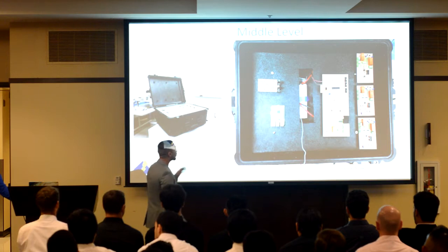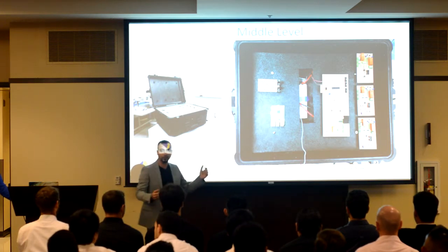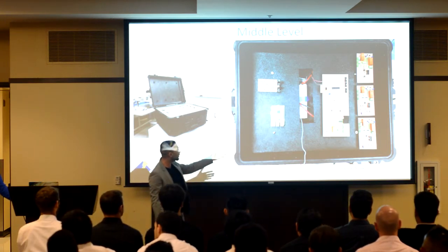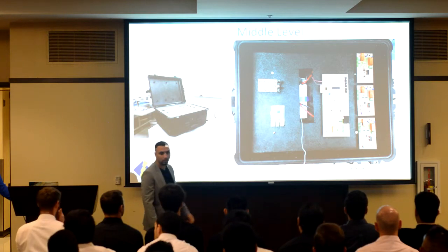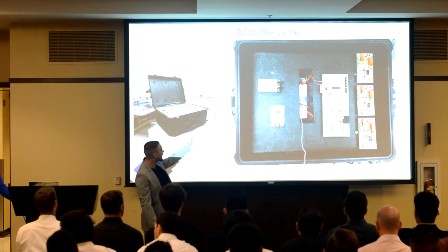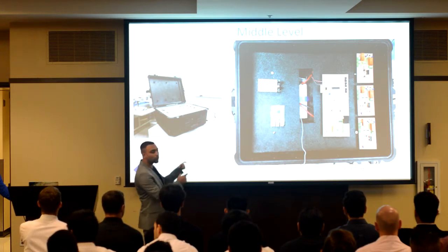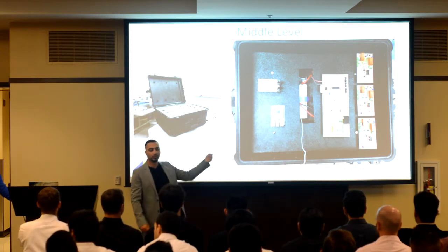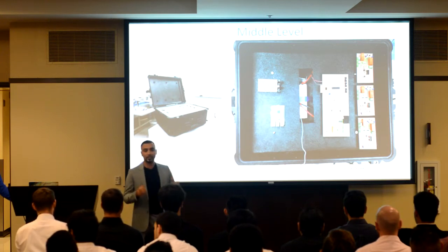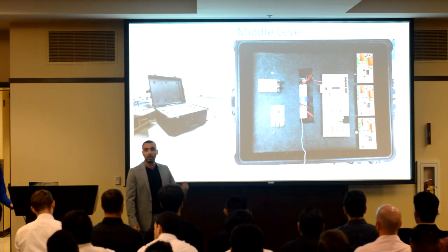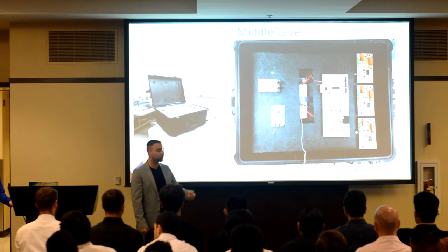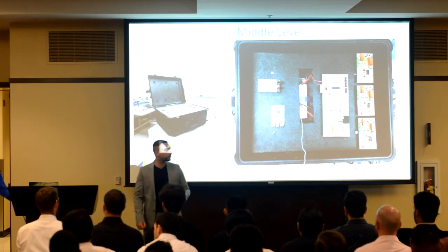Next slide, please. So this is what goes underneath the faceplate. We have 3 mini PCBs that are connected to a main bus board that is connected to the battery, the inverter, and the Raspberry Pi. Each one of these mini PCBs is going to be connected to an AC outlet, and each one of them will have a relay, a voltage sensor, and a current sensor. And Jeff will be explaining more about these sensors.